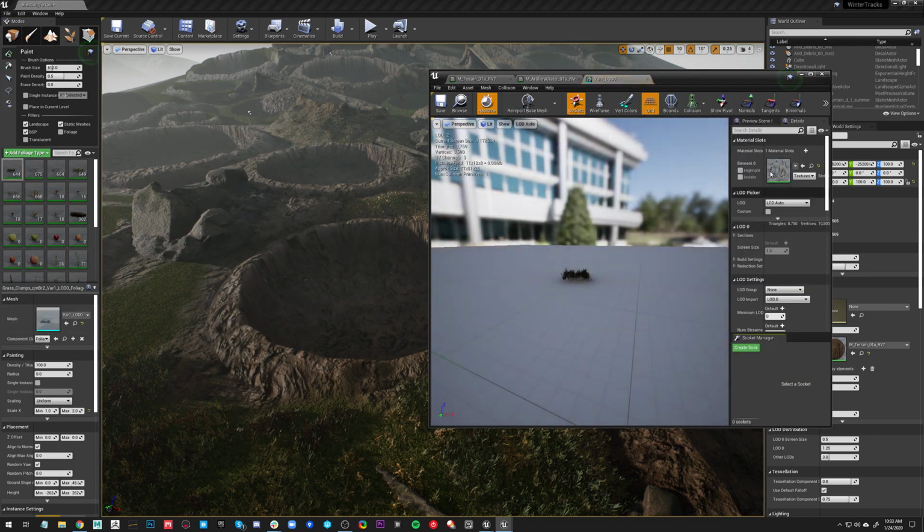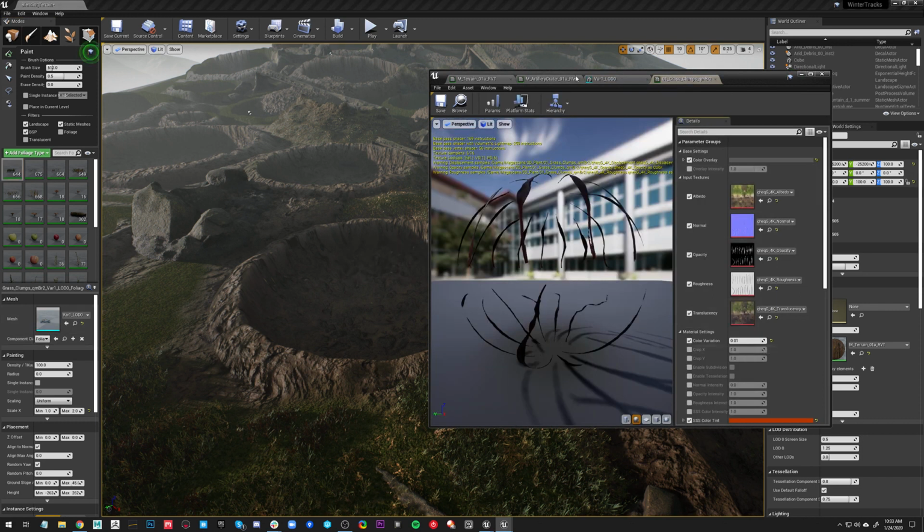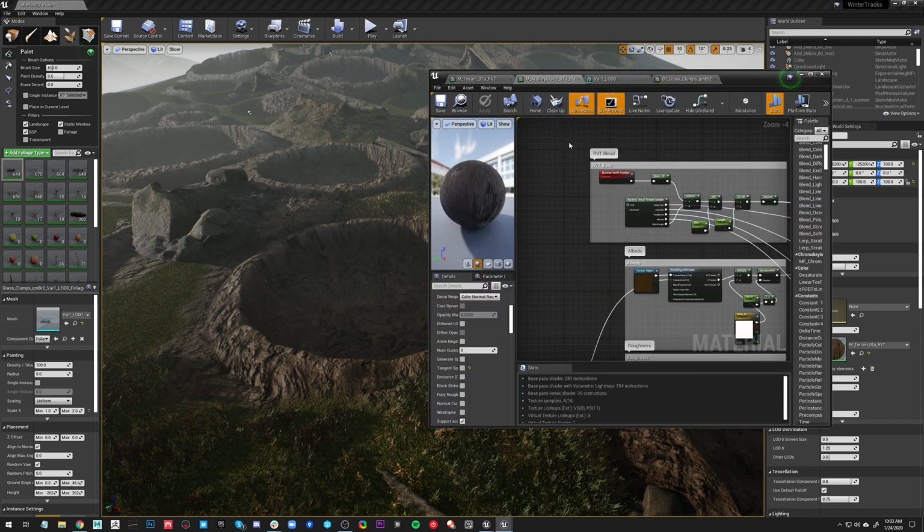Before you get too in-depth with that, I have a pretty good question from Tural Memedov. Shoot. He would like to know that if he has an expensive terrain material with distance fields blending, can he sample or convert that shader to RVT and get a cheaper version of the same shader? Yeah, so basically all of the expensive part is coming from the crater itself, because that's where all of the distance field math is happening. So all you'd really have to do is swap that out with RVTs, and it would be quite a bit cheaper.